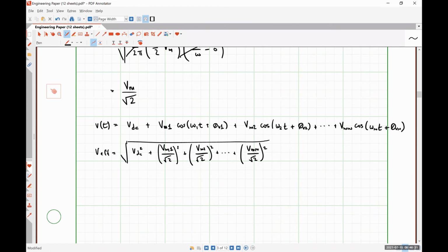But most of the analysis that we are going to do with complex power and designing systems and all that kind of stuff is at steady state. So we're only going to be paying attention to these RMS values and the average power, apparent power, all that kind of good stuff, because we're looking at it under steady state conditions, not under transient conditions where things can get a little bit wonky. There definitely are some applications where instantaneous power is important, but the overwhelming majority of applications are paying attention to the average power quantities.